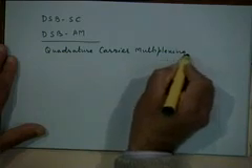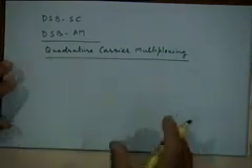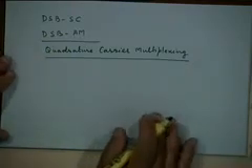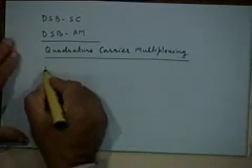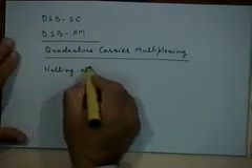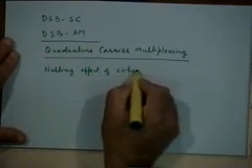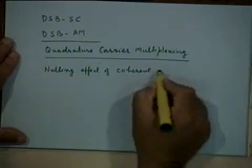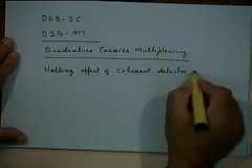That is, you can put two signals on the same carrier, right? Normally we don't think of putting two signals on the same carrier. So we are here using the nulling effect of the coherent or synchronous detector to advantage.